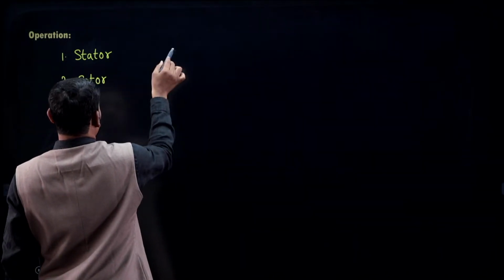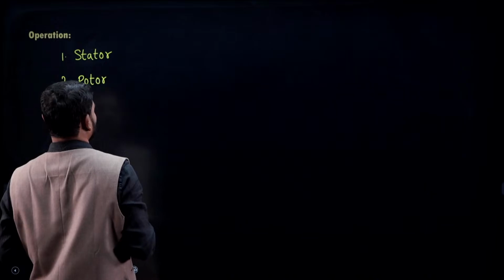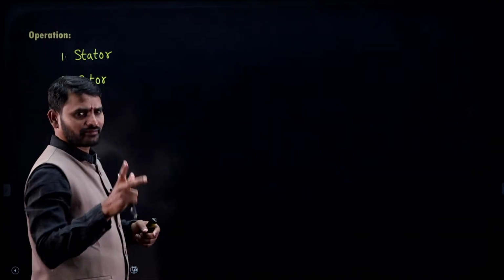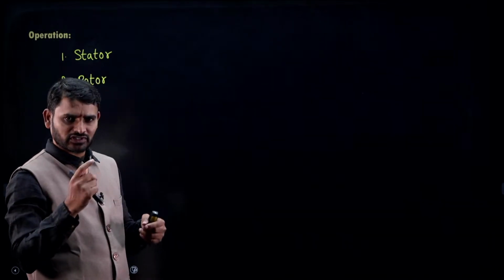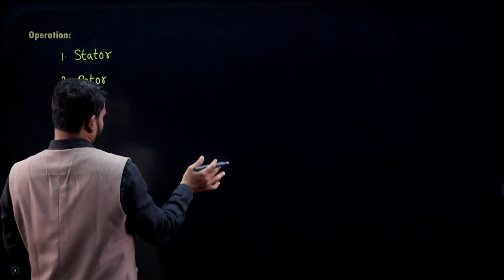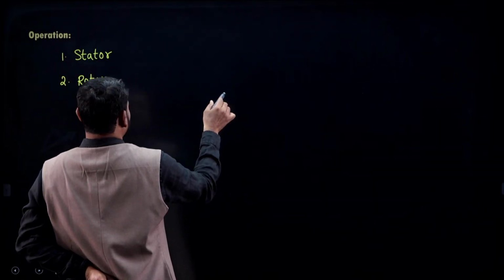So it is a hollow cylindrical construction and the rotor is going to be solid cylindrical, it looks like solid cylindrical, but you can make it laminations, thin sheets, to reduce eddy current losses. Okay. So let us not get into that. I just want to concentrate only on operation, because I have many questions on operation, especially slip, synchronous speed and all those things.